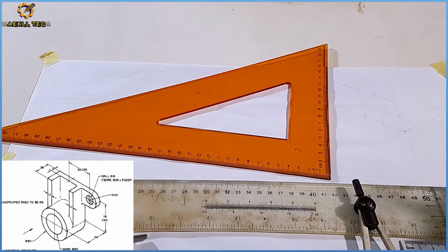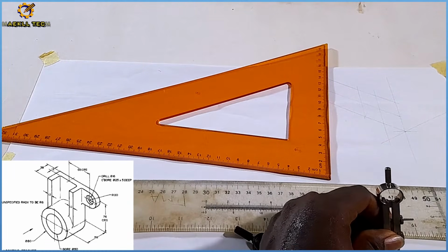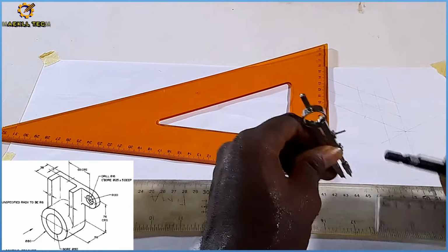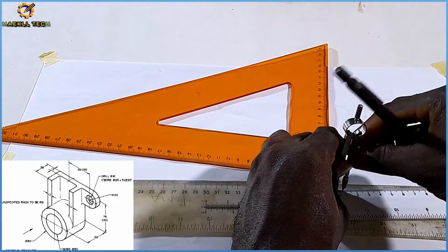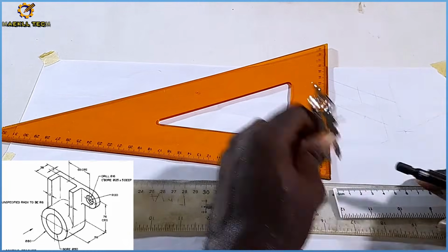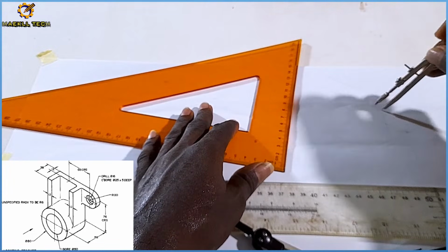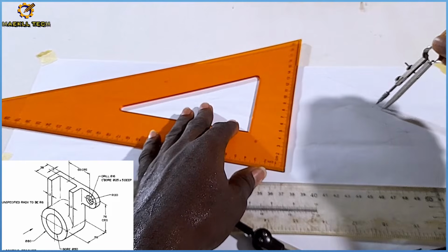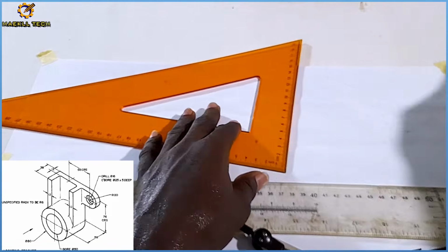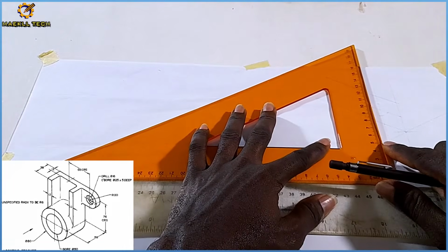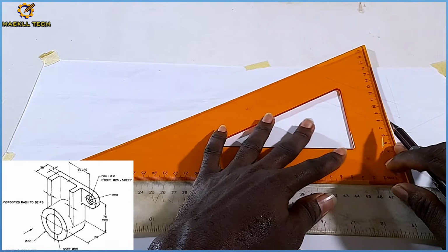what? Diameter 16. Now to get that drill of diameter 16, that will be radius, what? Radius of 8. So I'm going to pick my compass right here now. My compass right here, I open it to 8, radius of 8. With radius 8 on my compass, I stand at this midpoint right here. Do you see that? So then I mark on 4 cardinal points: left, top, bottom, and what? And right.